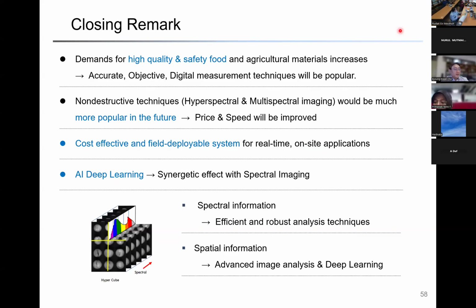Sometimes you need to wait 1 hour to stabilize your light source, and sometimes 10 or 15 minutes to stabilize your sensor. You need to check your system calibration and stabilization. That is very important. Otherwise, the measurement keeps changing, and even though you have a very good model, the performance is not good. Okay, thanks for the question.